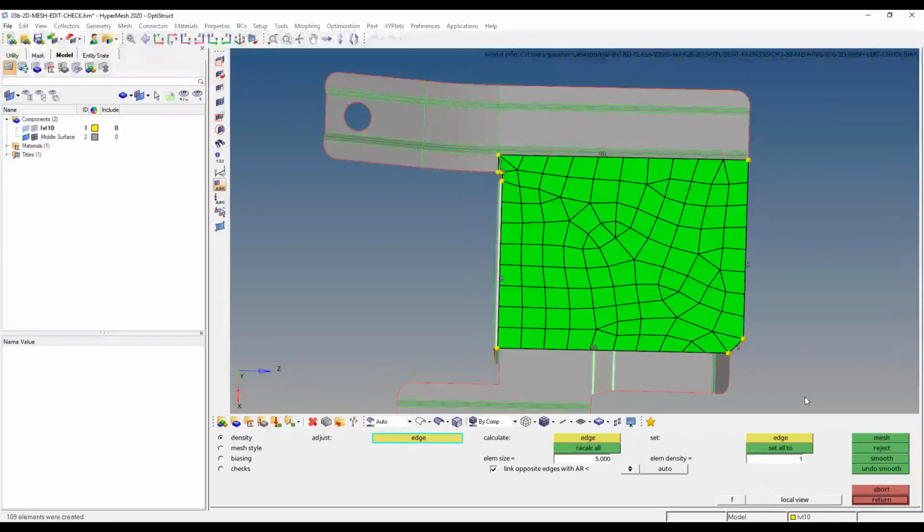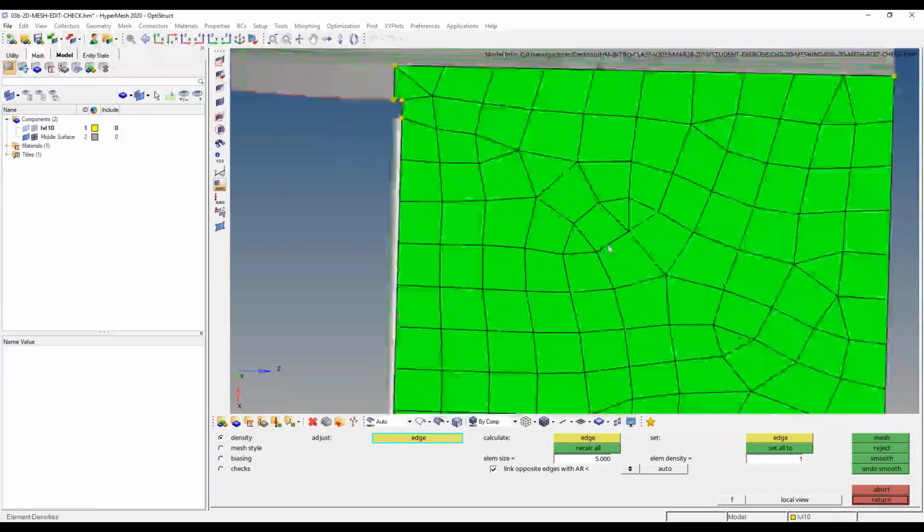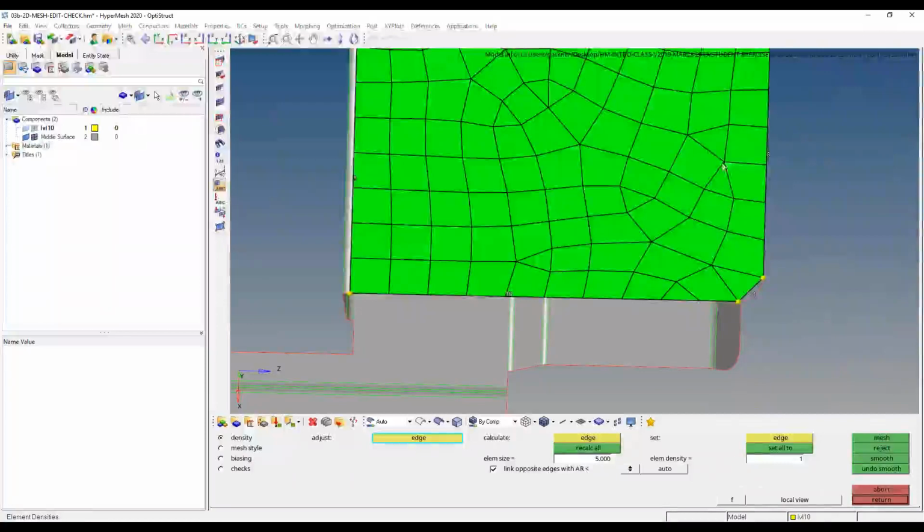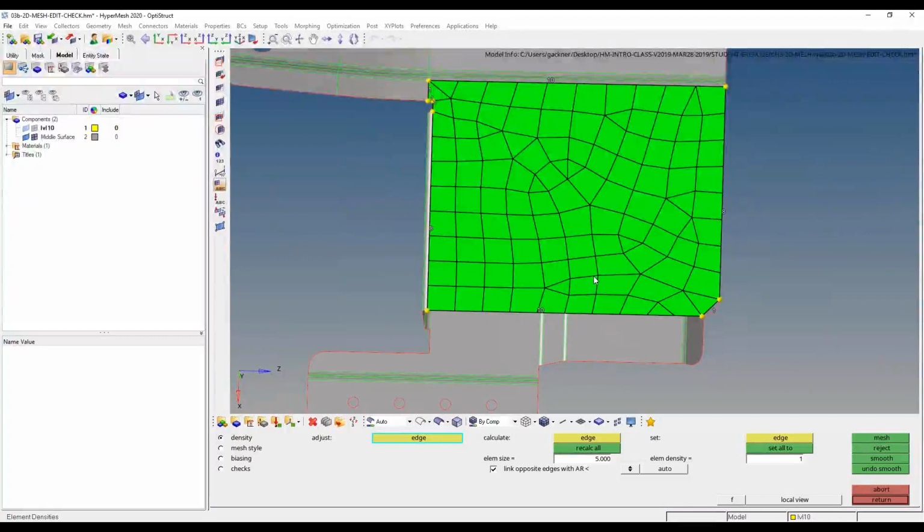But when I meshed it, for whatever reason, it's got this radial flow where it's not that boxy. It's got all these wavy lines, and I'm not sure where this semicircle profile of edges wanted to form. Let me get that spotlight tool. This is the edge line I'm talking about here. I'm not thrilled with why it's got this curved profile going through the mesh. Same thing over here at the top, just not as grid-like as I was expecting. So one of the things I'm going to do is adjust the topology or refine this geometry to help it out a little bit.